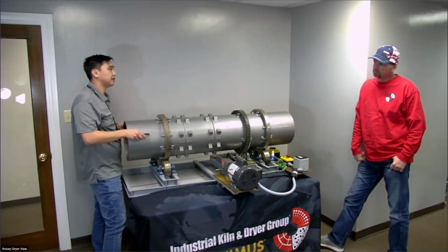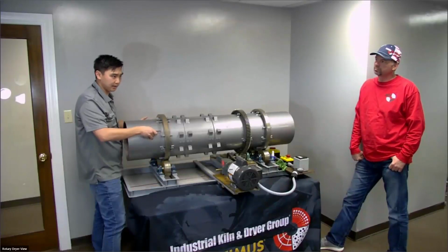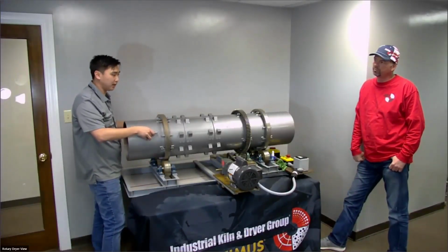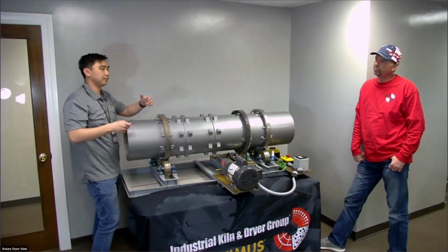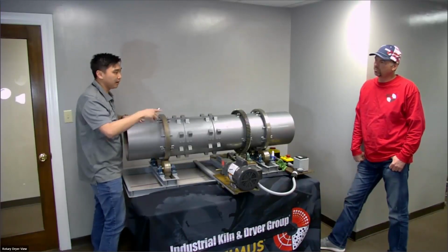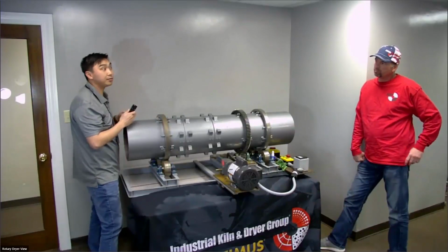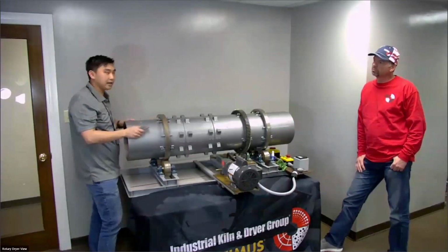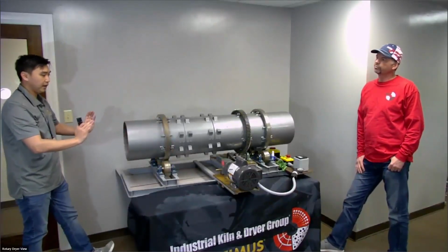If your material's still kind of wet, still clumpy, this is where the mixing slides go, and I'll show you the mixing slides in a little bit. So this will break up the clumps, and then almost all of this over here will be your lifting slides, your Sawtooth Flights, et cetera. And then sometimes, maybe over there at the end, another mixing slide if you want to gently convey it back out. And that is for a direct heat unit, so your burner's over here, okay?